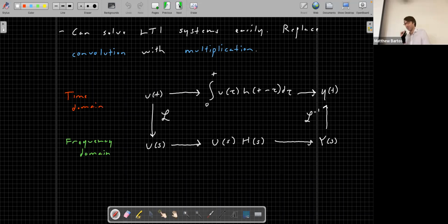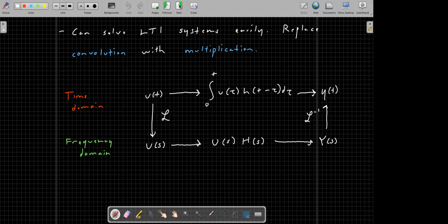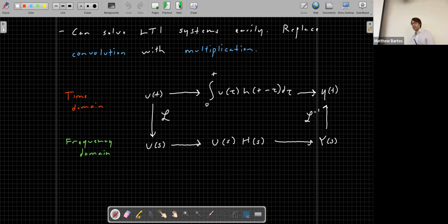And what is the impulse response function in your own words? I want to jog your memory a little bit because we haven't met for a while. What is the impulse response function? Just in your own words. The response that you would get for a particular Dirac delta function or a particular impulse. Right. So it's the response of the system to an instantaneous impulse as represented by a Dirac delta. Very good. So it characterizes the response of the system to that impulsive input. And then by treating our general input to the system as a train of Dirac deltas, we can compute the overall response to any input.